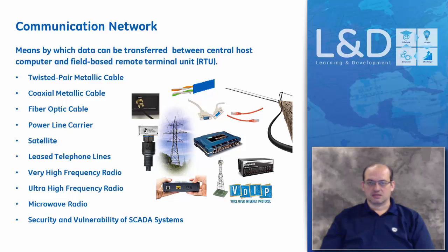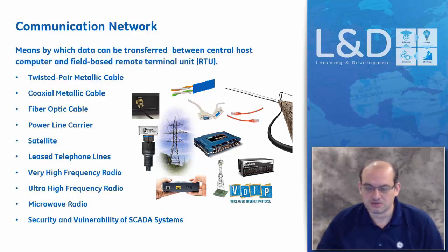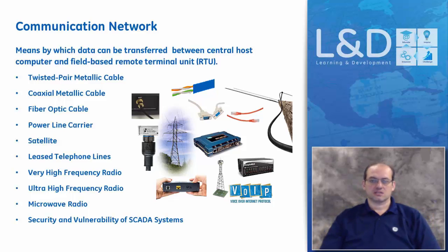A leased line is an expensive investment because the utility has to purchase a line per substation, which is not a cheap solution. Dial-up can be used where the substation is not critical, and the information can be accessed on a periodic basis, like every hour, every half an hour, and so on.